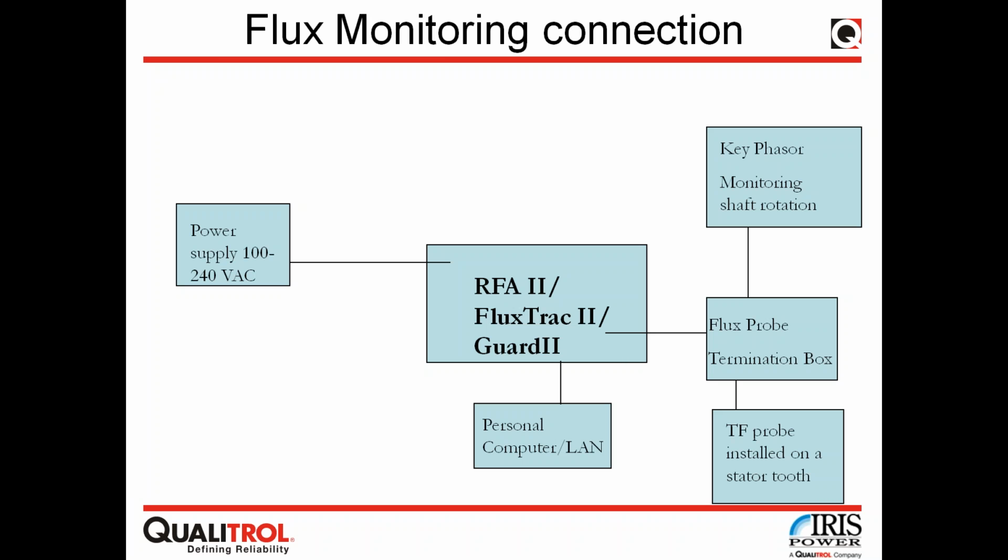So if your motor is large enough to be a significant candidate for PD monitoring, then with one instrument, which is a Guard, you can have PD monitoring, you can have flux monitoring, and maybe you can have shaft voltage and current monitoring on that motor.